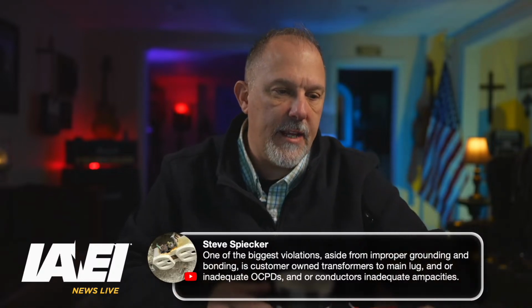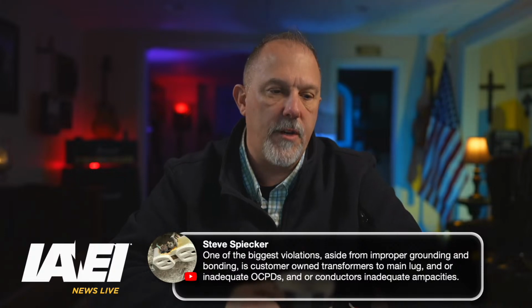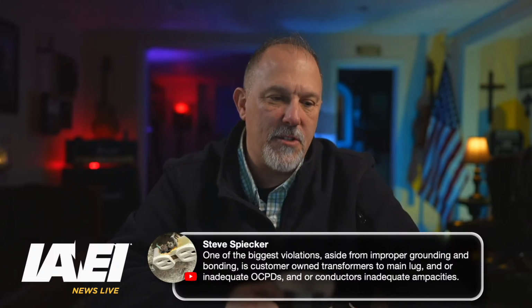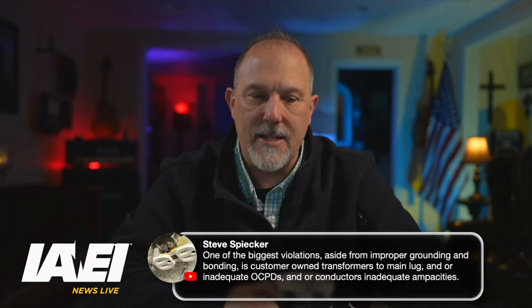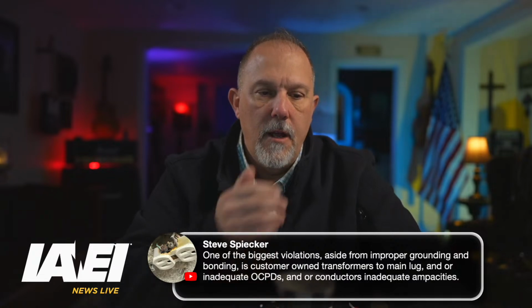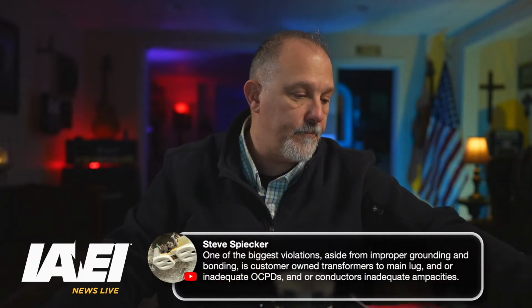One of the biggest violations, aside from improper grounding and bonding, is customer-owned transformers to main lug and/or inadequate OCPDs and conductors, inadequate ampacities. I agree with you 100%, Steve.